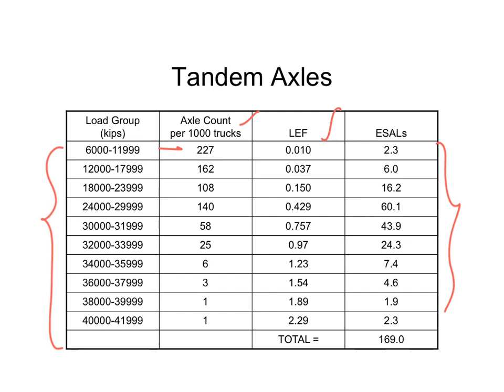Now if you have single axle and tandem axle and different classes of load, you have to make this mathematical computation for all groups for the whole design period. There is one more way to do that. We have data for single axle, we have data for tandem axle. For both we have taken the count of 1000 trucks, and we have calculated the equivalent single axle loads.